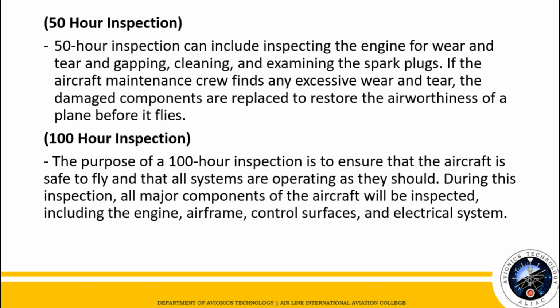The 100-hour inspection is typically performed by a certificated mechanic who is authorized by the FAA or CAAP to perform maintenance on the aircraft. It is required after every 100 hours of flight time or every 12 calendar months, whichever comes first.